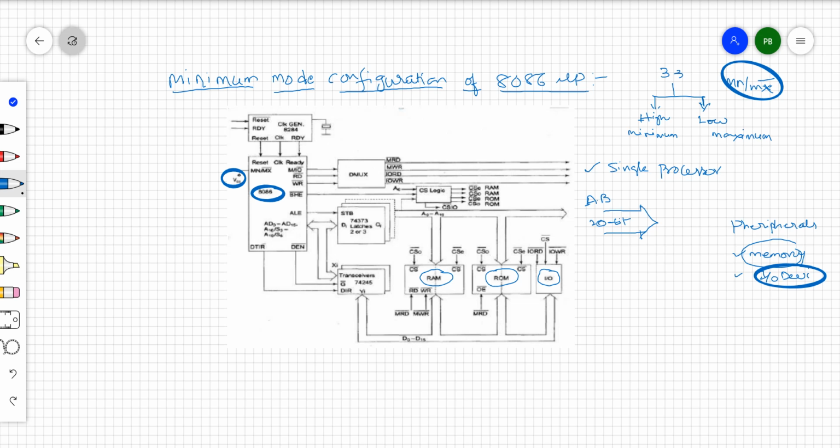It is used to address some memory or IO. Once it addresses memory, it addresses some register in the memory. In a similar way, for one among the n number of IO devices, the data going out through the 20 address lines of the address bus of the 8086 processor is used to address one register among the memory or one device among the IO devices. That means it is addressing.